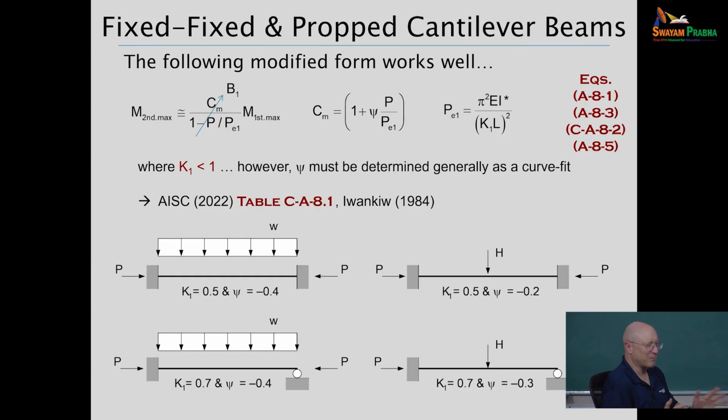So I'll compare and contrast a bit, but I didn't want to come here and lecture you, saying here's how we do something in America, and that's nothing like what you do here in terms of stiffness reduction. I'll give a few reasons why we think it's a good way to go in the Americas, and then I'll leave it there. So the EI star is where, at least in the Americas, we sometimes implement a reduction on the bending rigidity as part of our elastic analysis calculations.